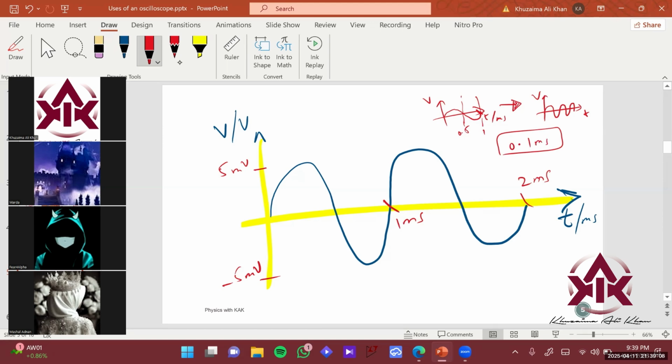If I increase the time base setting, it will make the display more zoomed in. If I set it to 3 millisecond, my time-based setting is basically 3 millisecond per division. That means one box will capture 3 millisecond. So in this setting, my two boxes on the oscilloscope screen: the first will hit 3 millisecond, and the second one will hit 6 millisecond over here. So I would capture basically 6 waveforms here.